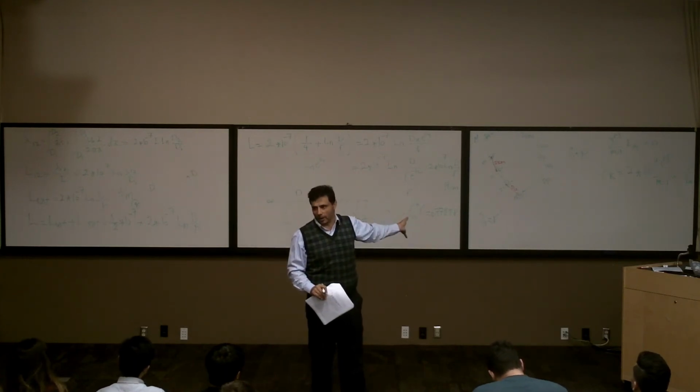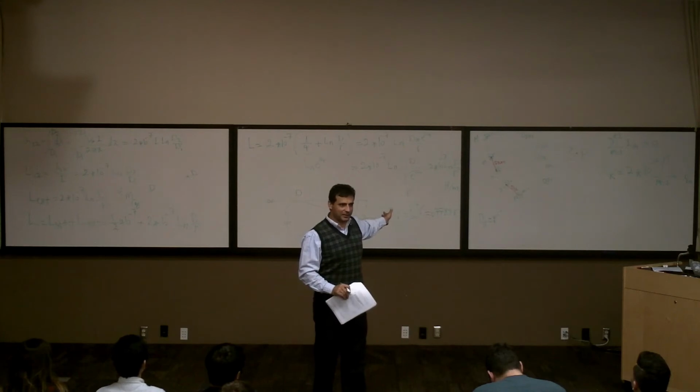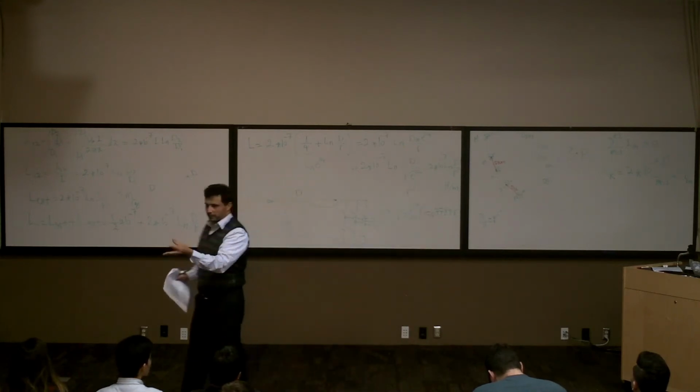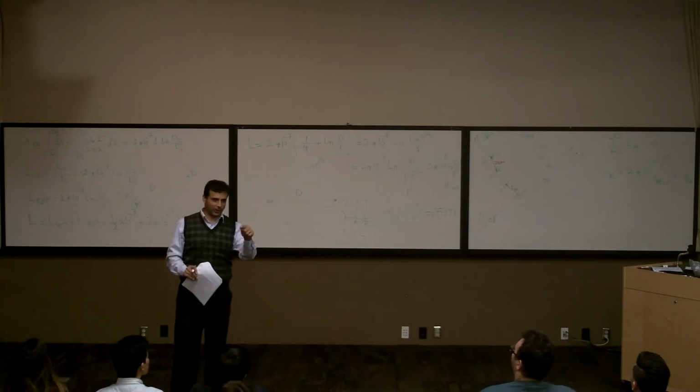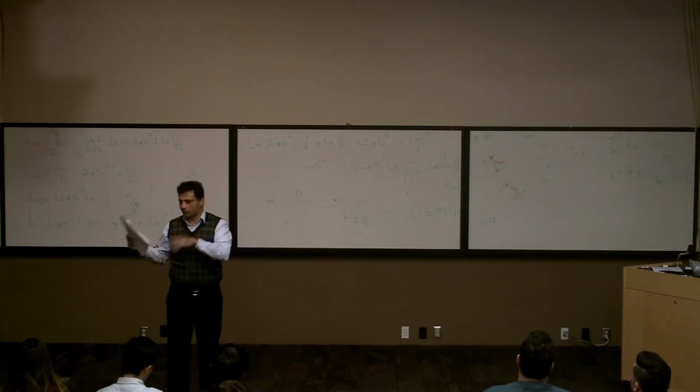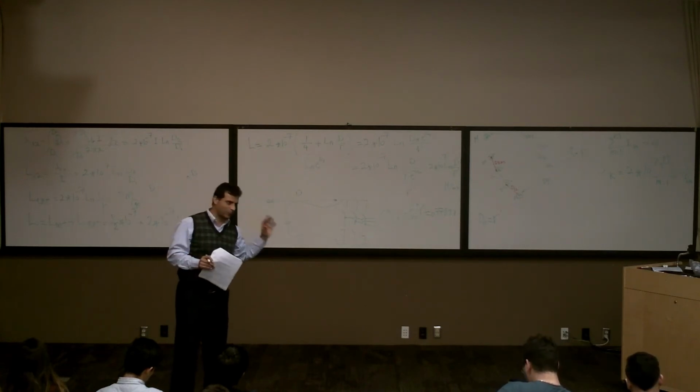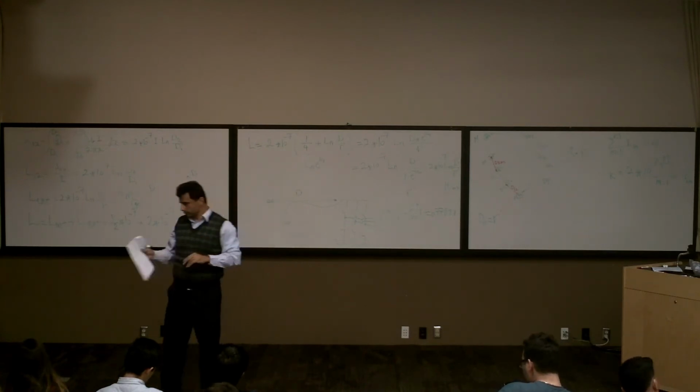And how much is R prime? It is 0.7788 R. You can look at all these systems. It's not like one of the strands is bigger or the other one is smaller. They are all the same. My point is, all of them have the same cross section, right?